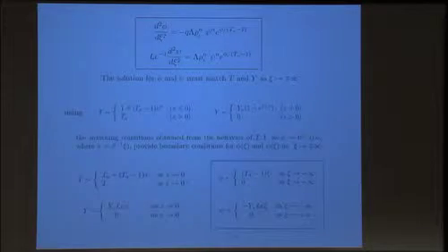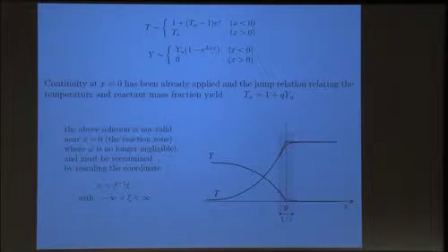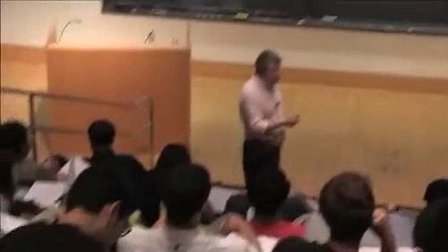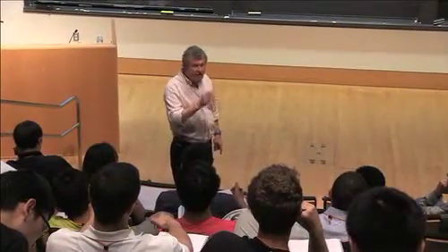solution is, where is this? Here is an exponential, right? And if you take the exponential of 5 units, you obtain approximately 0.01. So the drop of the temperature from this point to nearly the cold temperature is approximately over 5 units of LF, the diffusion length. So the true flame thickness is 5 LF, it's not LF.